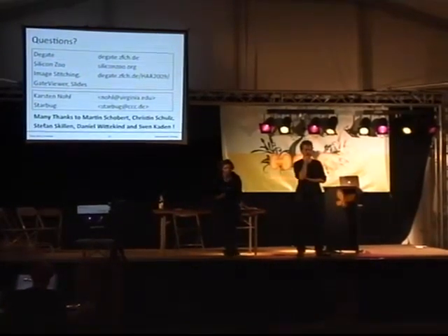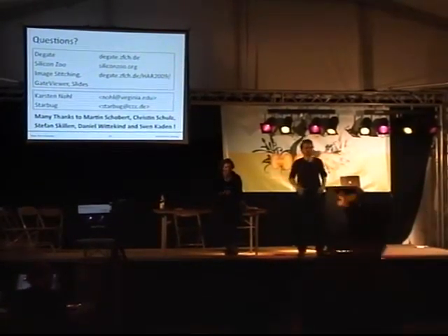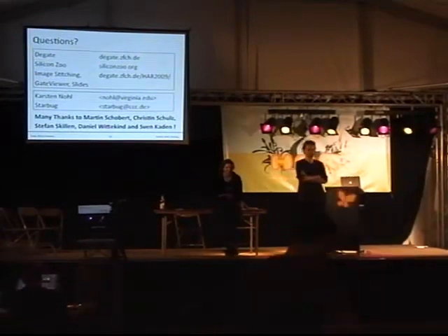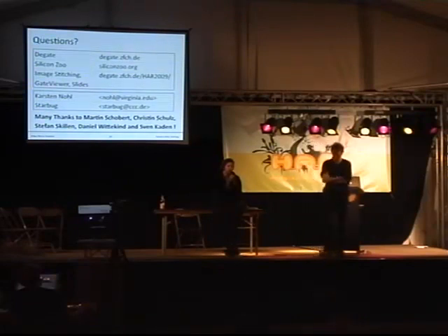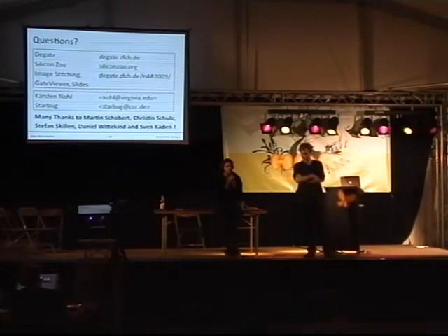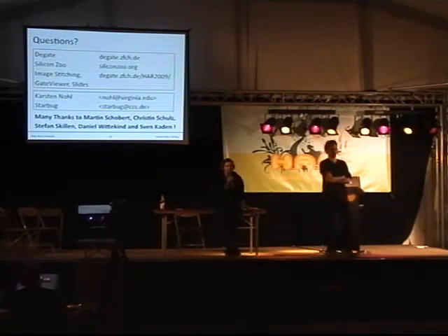I missed most of your talk, but how many metal layers can you actually do? And if you polish them off, how do you do the coplanarity of the layers? So you're not polishing off half of the next layer and then not getting images. So the chip with the most layers was the MIFARE chip. It had 6 layers, but you are not limited to any amount of layers.